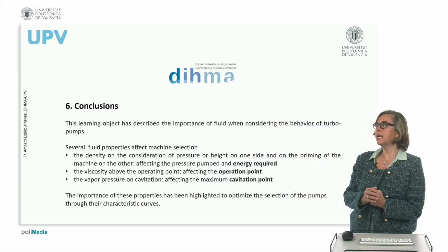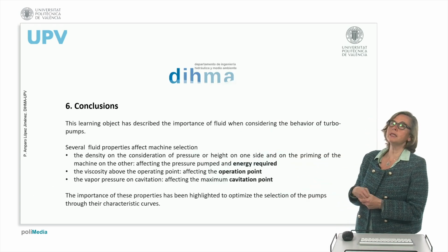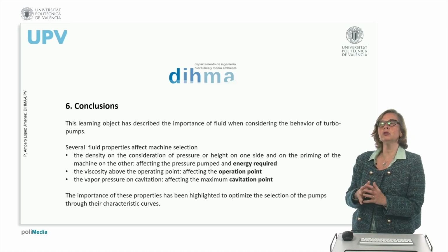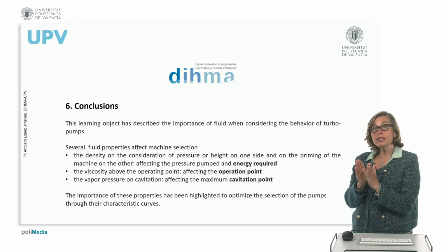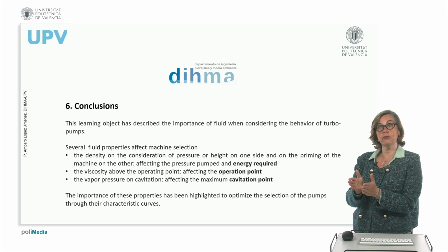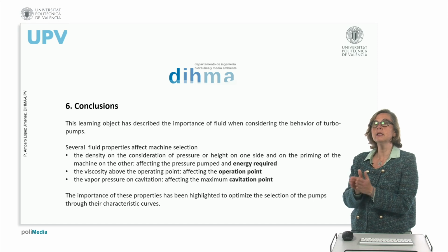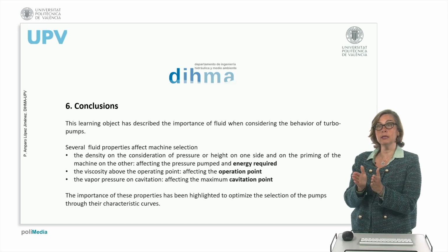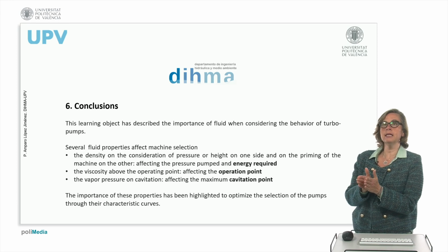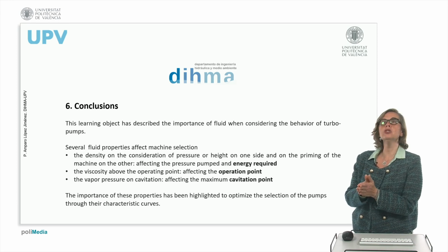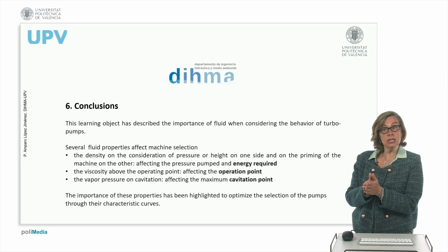So, as we have indicated, these properties of the fluid affect very much the selection of a pump. They affect the energy required in terms of pressure, viscosity and density, affect the operation point, affect the cavitation point, and affect the selection of the machine at the end.